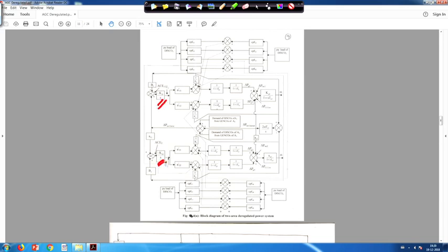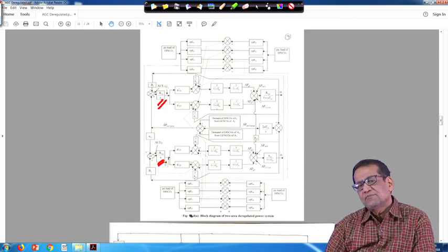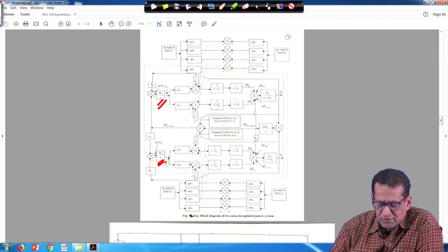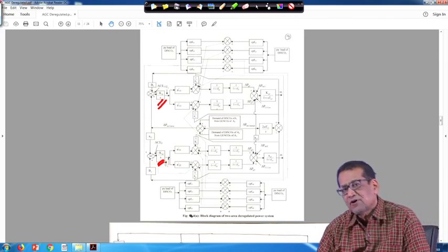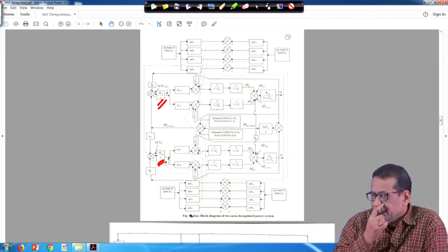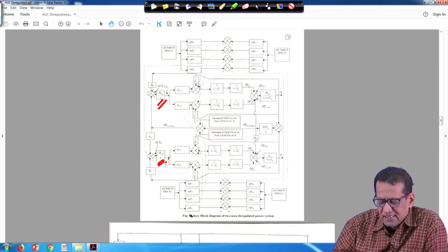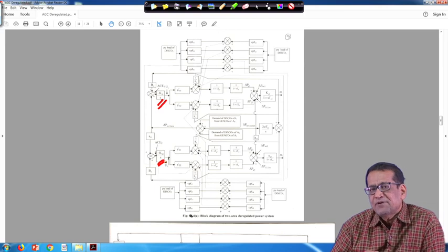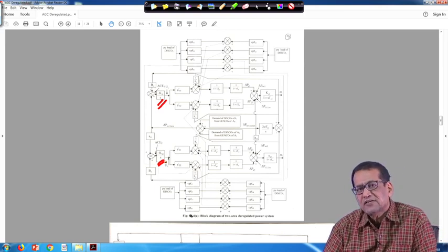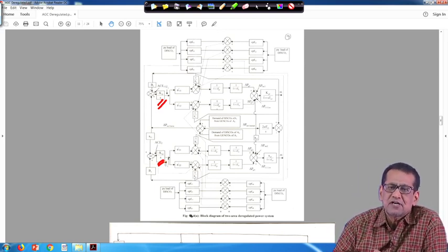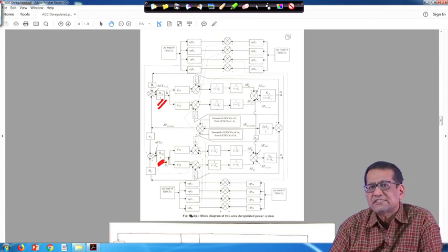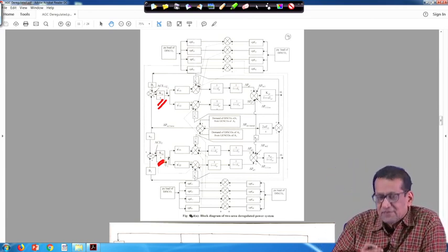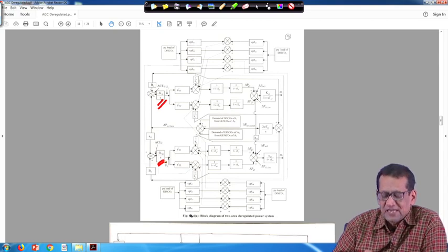Then this is the integral control error in area 1 and this is the integral control error in area 2. We have taken integral control only, but you can choose other types of controller. From a practical point of view, utilities generally prefer the integral controller or proportional integral controller, but not a derivative controller for a thermal system. Derivative controller for a thermal system is not recommended.